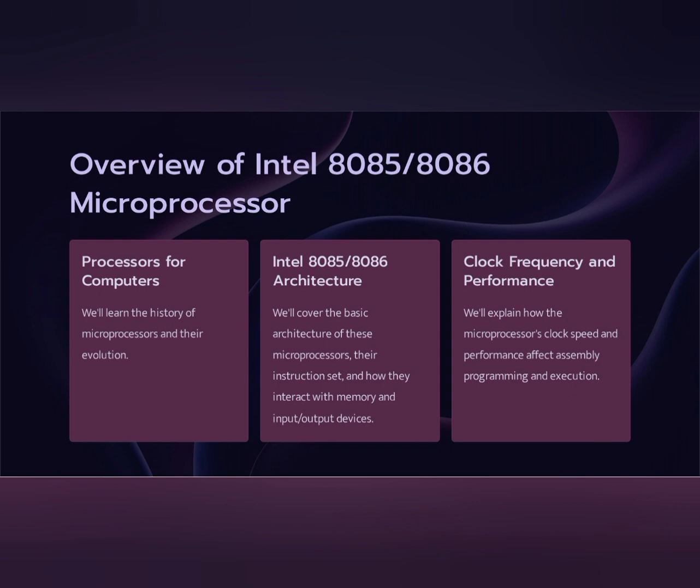The Intel 8085 microprocessor architecture has an 8-bit register file consisting of 6 general purpose registers and 2 8-bit internal registers and various specific purpose registers. It has a 16-bit address bus and can access a total of 64 KB of memory. While the 8086 is a 16-bit processor, meaning that it can process data in 16-bit chunks. It also has segmented memory management, which allows for efficient management of memory and better resource utilization.